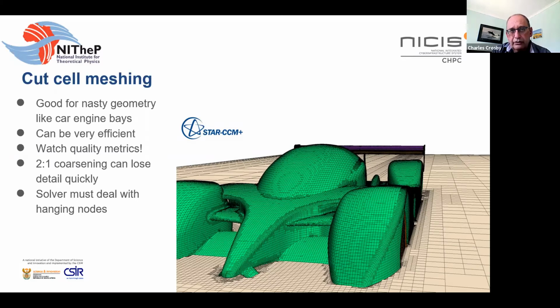Very often you know what you're doing the analysis for, and it may not be critical to have grid independent results, but if you're going to be comparing different ideas, they need to be working at a similar level of mesh resolution if your relative answers are going to be reliable. So you should not compare fine grid results to coarse grid results. Ideally, you should always use a grid that's fine enough. Practically speaking, that's not always possible. So then at least you need to be very consistent.